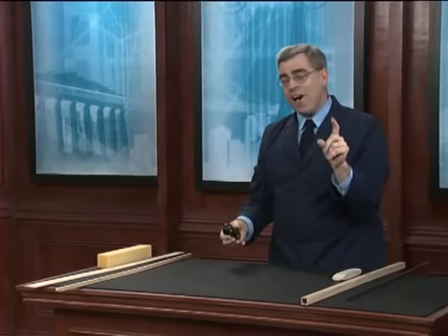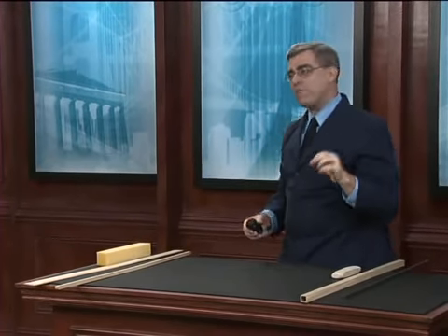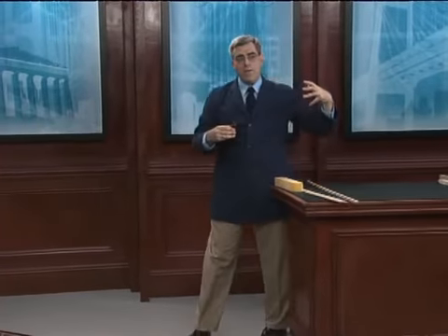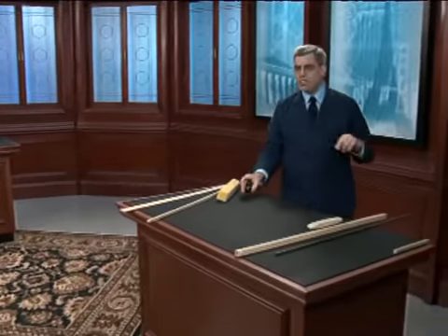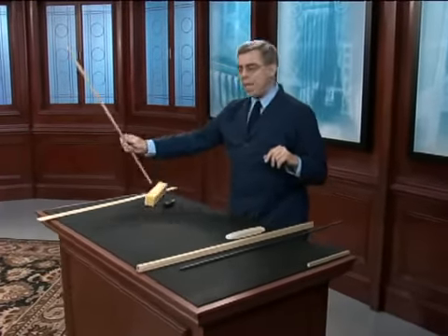Remember that all three of those columns used exactly the same amount of material. And so that wide range in their buckling strengths is a clear illustration of the benefits that we get from using a cross-section with a large moment of inertia. Finally, we want to investigate the effect of length on buckling strength. So once again, let's return to the demonstration table. And this time, I'm going to once again start with my baseline column.